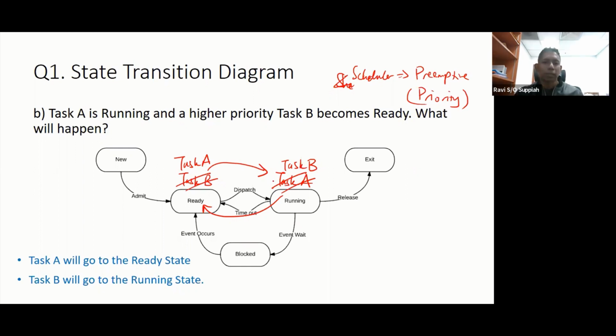So it is not possible for a task to be in the ready state and no task is running, because the moment you are in the ready state means you have everything that you need to run, and it's the responsibility of the scheduler to transition you to the run state. So it's not possible to have all tasks ready and no tasks running.